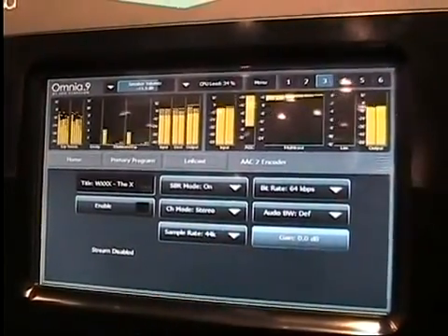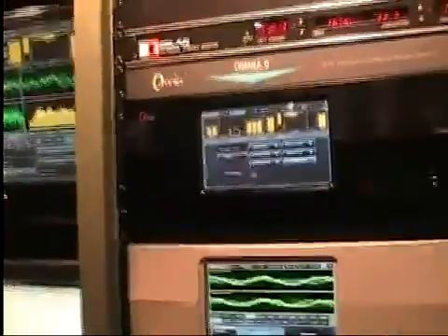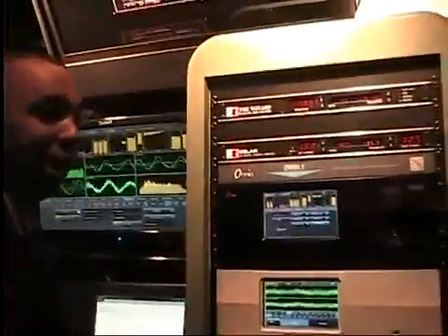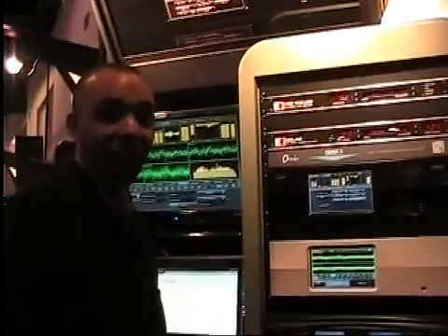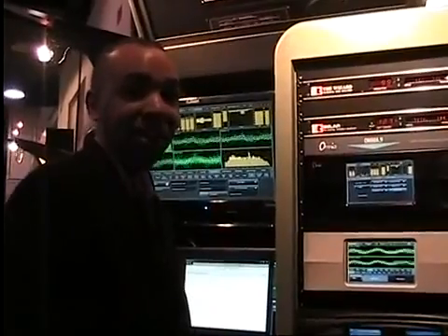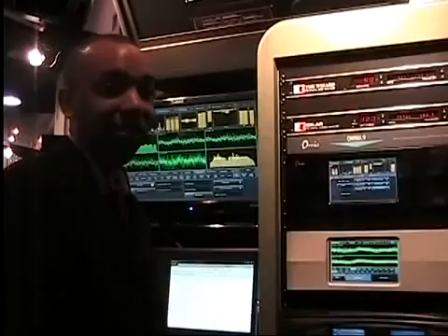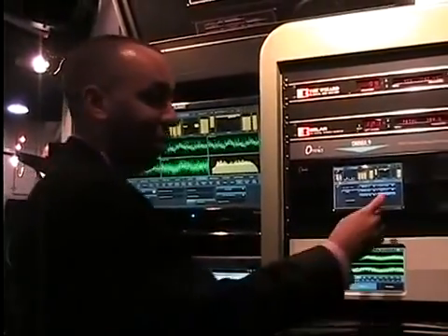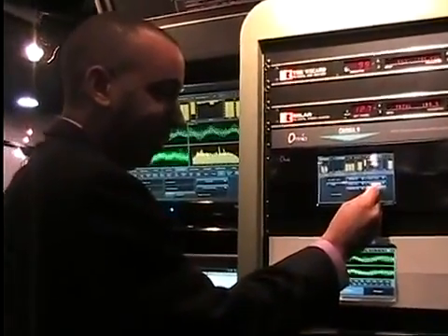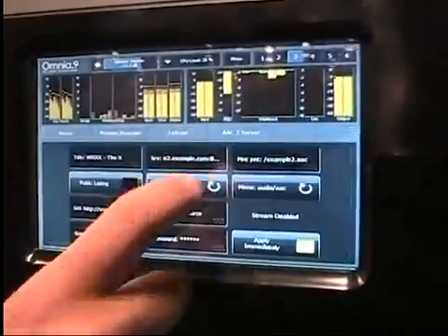For a low bitrate like this, if we're pushing the dynamics of the audio, if we're pushing the loudness of the audio with a lower bitrate codec, you're going to get distortion inside the decoder. So for that reason, there's a separate gain adjustment control for each encoder. For AAC Plus at 64K, I happen to know we should be turning it down by 2 dB. So let's do that. There's that.